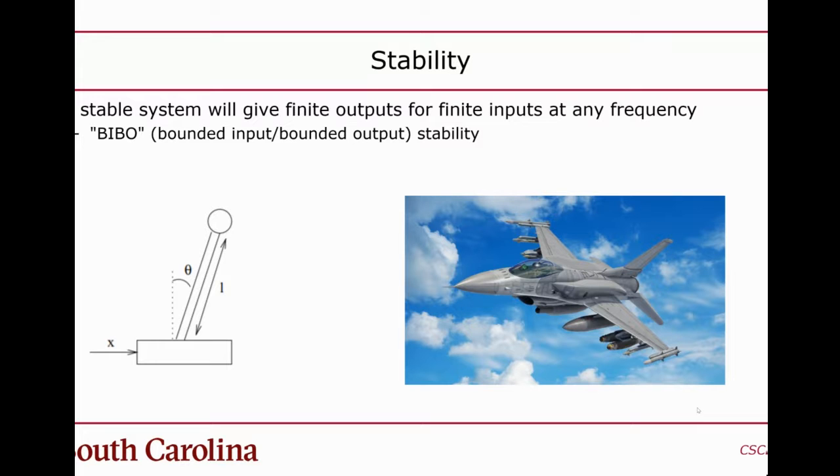And in fact, the human body is actually an inverted pendulum. If you think about it, in order just to stand and walk around, you have to constantly make control decisions. You have to stay upright and balance yourself. If someone were standing and suddenly went unconscious, of course, they would just fall on the floor. So that's the idea: the pendulum by itself is unstable. It needs to be stabilized by a controller.